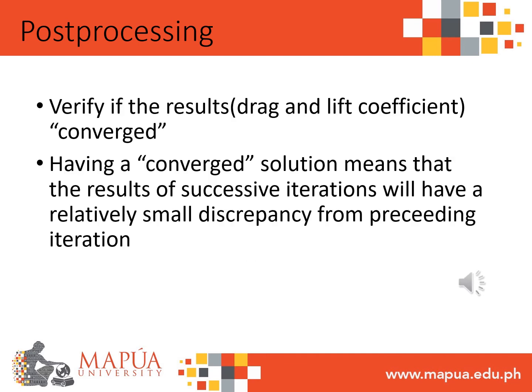Aside from visualizing and getting the results of simulation, we can also verify our results in post-processing. We can verify if the solution of our simulation will converge. Having a converged solution means that the results of successive iterations will have a relatively small discrepancy from the preceding iteration.